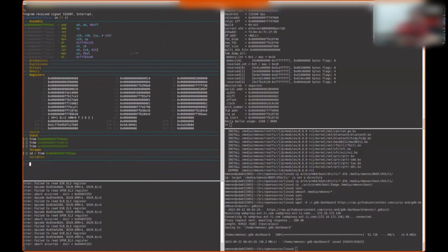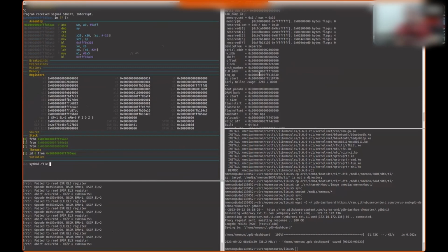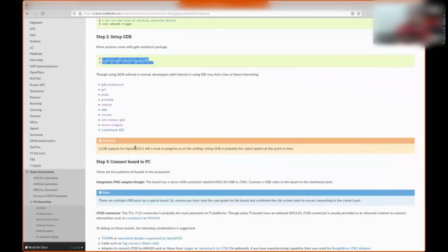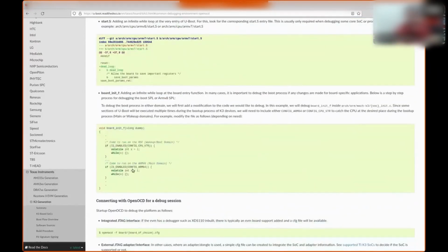And the reason for that is that U-Boot has done a relocation. If you remember, previously we had spoken about this reloc address, and that's the address that we need to use here. For the sake of our sanity, this has been documented.